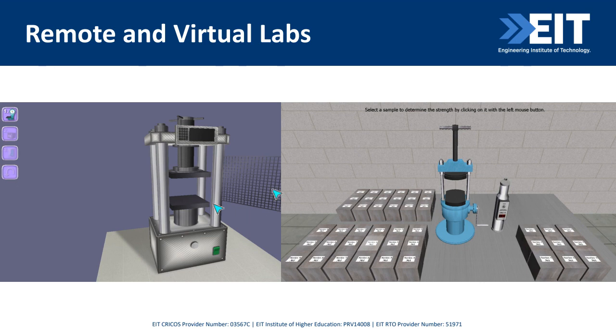And here, just to illustrate, as structural engineers, this is something that I did during my doctoral degree. One of my favorite areas is non-destructive tests. It gives us an opportunity to understand the structural behavior in situ, but you can also collect samples from existing structures, bring them to the lab, and conduct a rebound hammer test or ultrasonic pulse velocity test.